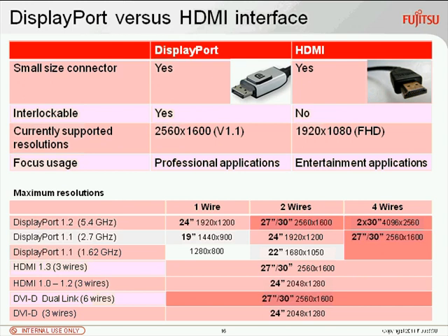So now I will come to some items that are not panel related but also quite important for the display. For example, the interface. So the resolution of the displays is getting higher and higher. VGA, DVI interfaces, which are common, often are not good enough to support the resolution. That's why mainly DisplayPort interfaces are coming up more and more, especially in professional displays.